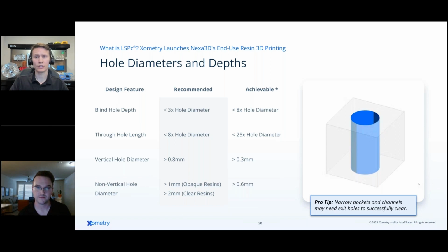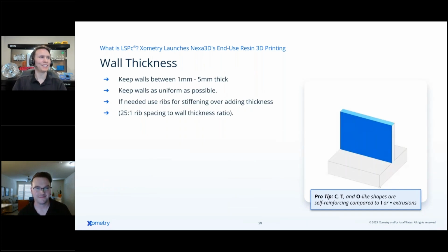Yeah, the cure through can also make your holes look a little oblong if you go too small. And even in heat-based systems, like powder bed fusion, I'm a powder bed fusion person, you always want to create a keep away zone as well, because the same thing happens thermally. If a hole is too small, the heat on one side of the hole is reflecting on the other side, and essentially it will just fuse the trapped material inside, and so you don't have a hole anymore. So this is why we have these design tips.